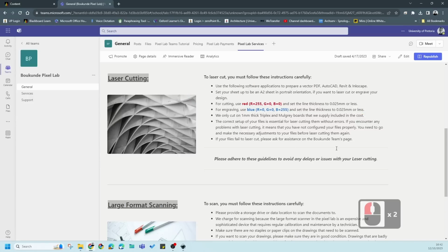Now that we understand this principle, just understand that the laser cutter, if you measure the cut line, it's 1 mil thick. So just remember, in real terms, you need to provide a buffer if you're going to be cutting a lot of different elements. You'll be wasting your time if you don't understand this 1 mil buffer. So just check that when we're doing your drawings, but that's something that I'll talk through in the workshop.